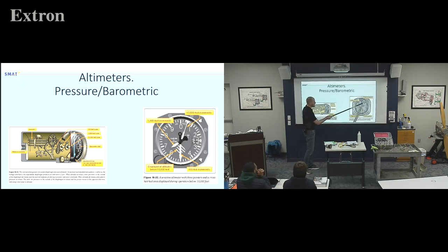They also have this one down here for a 10,000-foot increment. In our small planes, we don't use it much. But you'll notice it's halfway between 0 and 1, so about 6,500. If I were to fly all the way up to 50,000 feet, this hand is going to end up way over by the 50, and it'd be 56,500. So you've got 3 sets of hands on most altimeters to tell you how high you are.